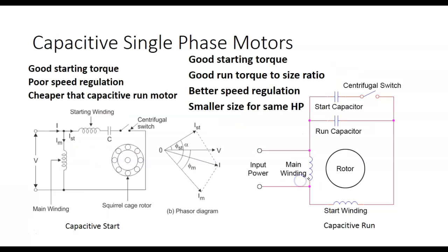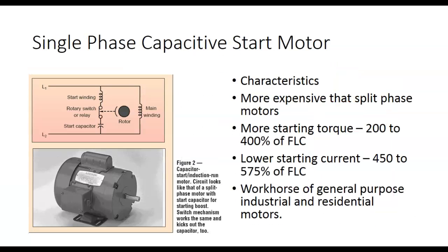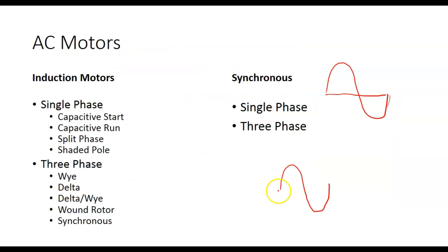So one cycle is generated on a circle. One repetition we call a cycle, and one repetition is 360 electrical degrees. So this right here would occur at 90 electrical degrees. It crosses at 180. Then it crosses again at 270 degrees. And then this right here would be 360. And it's just like 12 midnight.